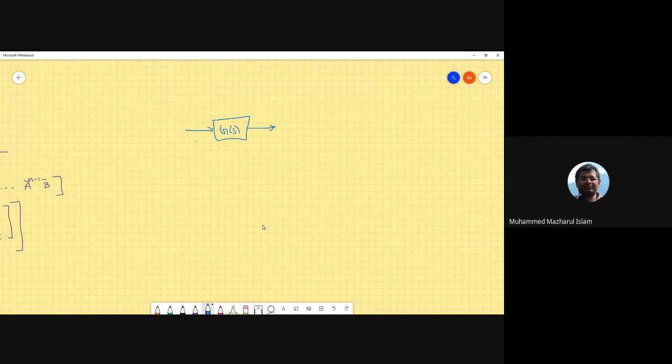We had an input. The input was called U(s), and the output is typically Y(s) in state space. Or you can also use R(s) and C(s) like we typically did. Doesn't matter. So ultimately, we used a state space feedback mechanism to produce our desired response. We could have also done this using root locus, couldn't we? In root locus, if I wanted to get the same performance, that is Ts equals 0.74 seconds, and percent OS equals 9.5%.